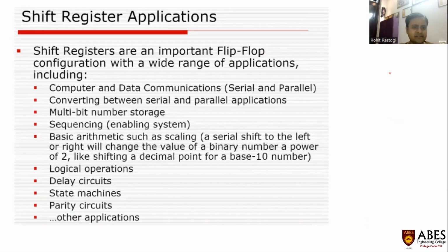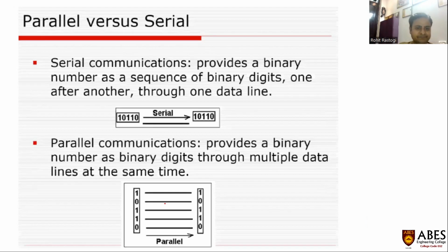Before starting the shift register, let us understand that they have a wide range of applications. They are used in computer and data communication, converting between serial and parallel applications, multi-bit number storage, sequencing or designing of the enabling system, and basic arithmetic operations, because we have a binary system. In conversion of a binary number to a decimal number, shifting can be done, and also logical operations, delay circuit generation, state machine operation, parity circuit generation, and many more applications are possible with the help of shift registers.